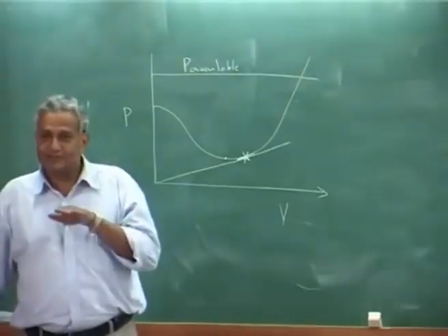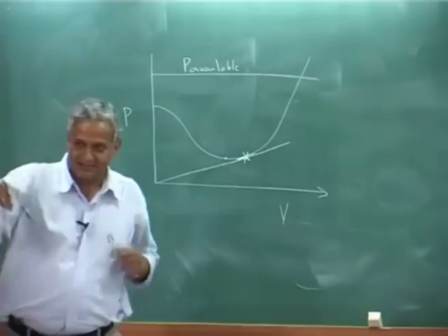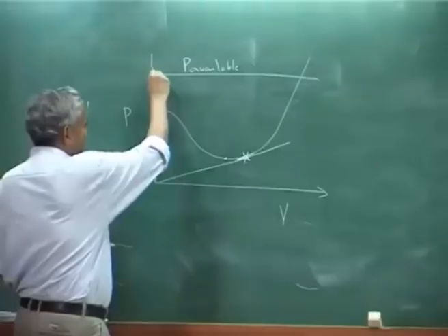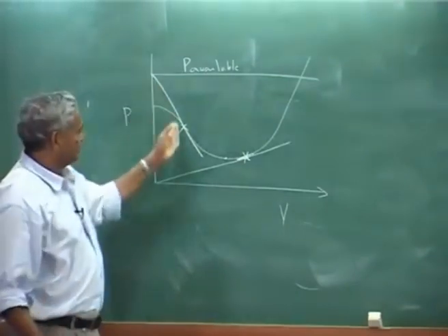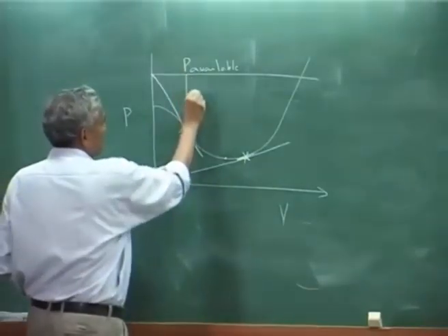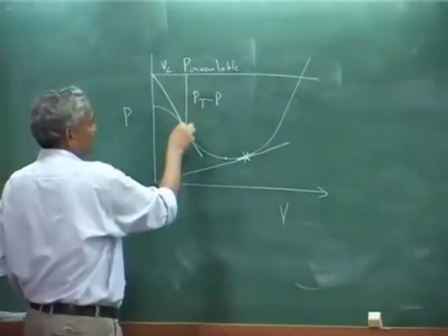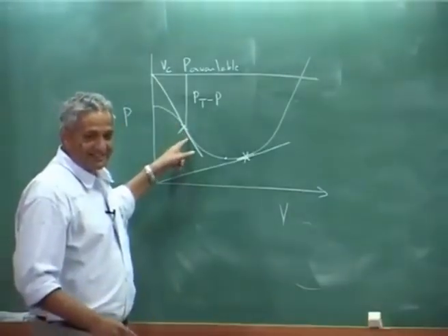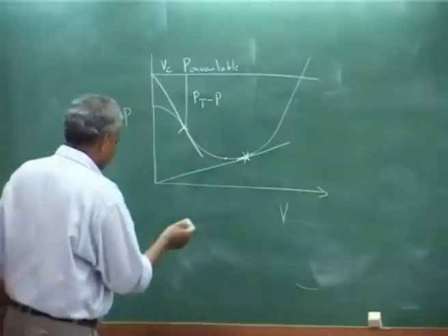What velocity if you fly, you will be climbing at the steepest angle, because if you want to clear something, the distance to that height matters. So, that is again the power available Pt, that is drawn like this point. You will know the slope, this is Pt minus P, this is V climb. So, slope of that is basically the tangent of that curve. That comes from this expression.